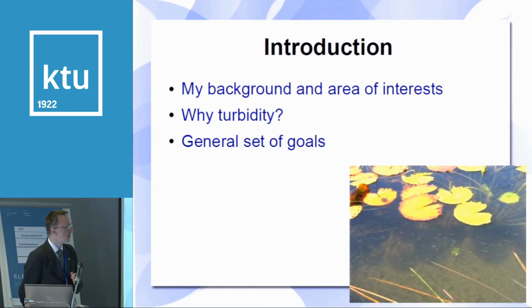Why turbidity? First of all, because it's one of the key parameters with which one can assess the quality of clean water or tap water or some other water. Secondly, because it's one of the few parameters that can be measured with just electrical or optoelectronic methods. Other water parameters need to be measured with chemical sensors or chemical methods that are applicable only in a laboratory, like spectrophotometry, which is not available in situ.